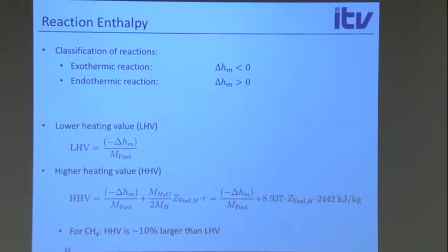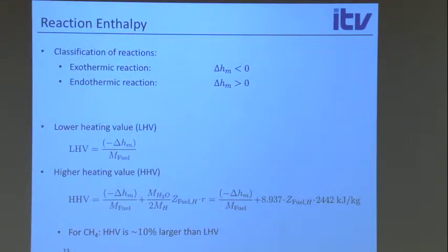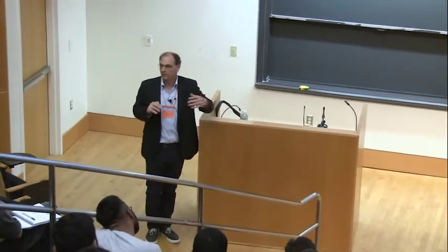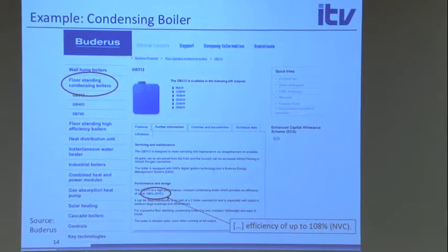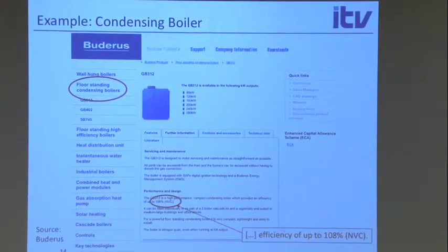So in the combustion process, the combustion efficiency, how much of the chemical energy you can convert into thermal energy, that's typically close to 100%. And if I then take the water and condense it, I get 10% more. This is why they say so. So they have a combustion efficiency of 98% plus about 10% because they compare it to the wrong value, really.